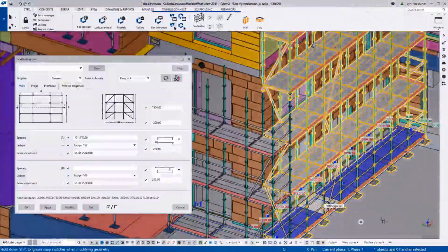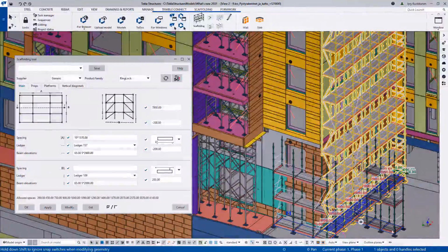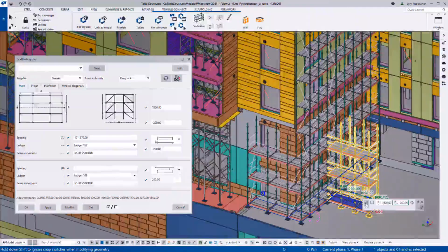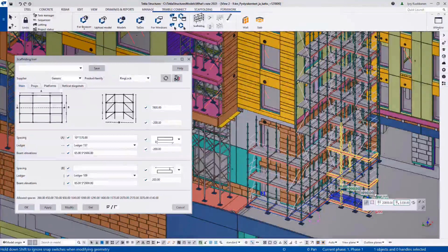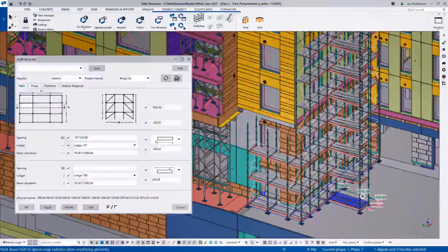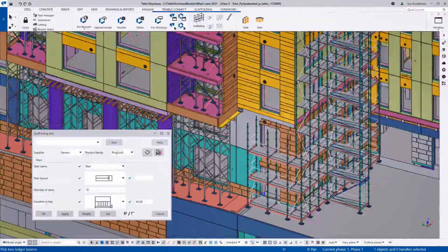So defining, for example, a new height for this section of the scaffolding. Or then if we would like to add a staircase for the scaffolding, creating a new section for the stairs, adjusting the bay dimensions to be good for the stair components, and then initiate the detailing tools. As the stair tool is using those ledger beams as the input, you can pick those and the previews will show where the stairs will be located.